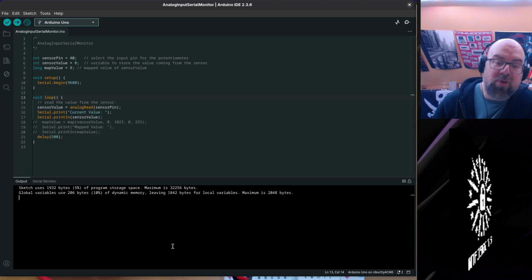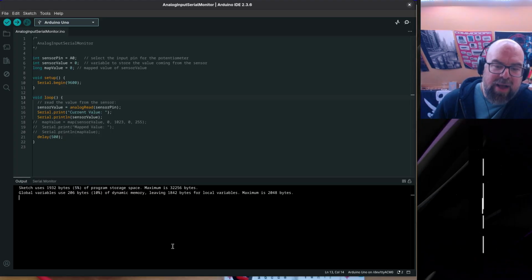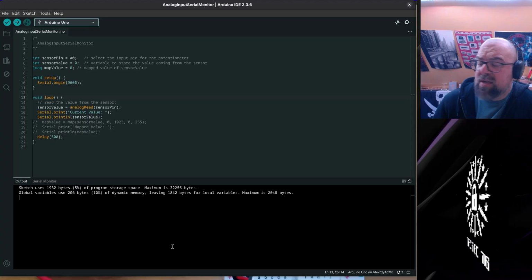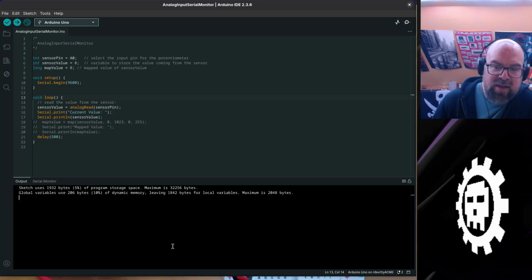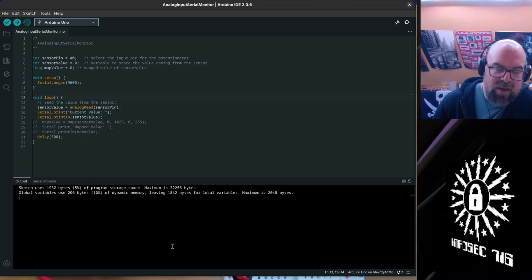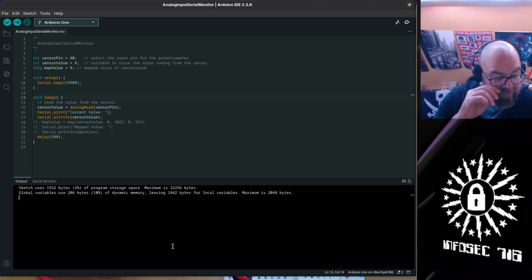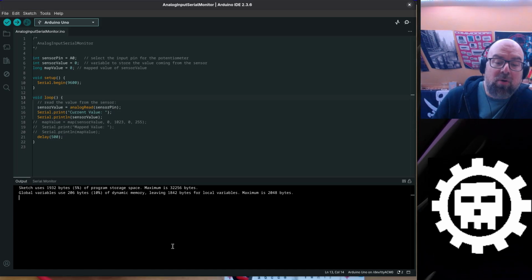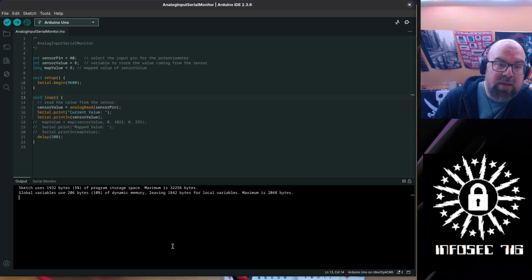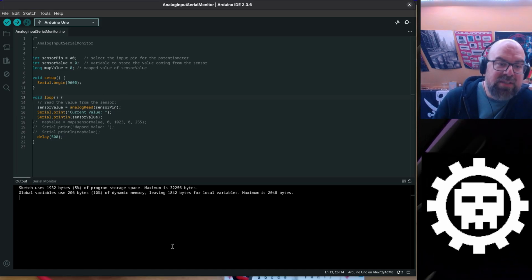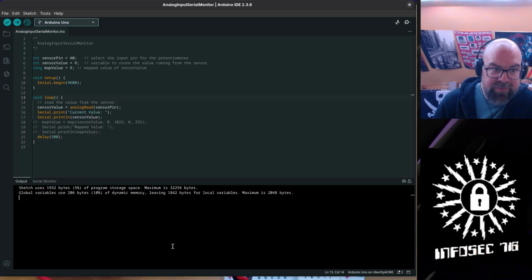It can really only produce a digital signal, but by turning it on and off, think like a strobe light, it can simulate an analog signal, by leaving it on and off for particular lengths of time. Anyway, so a PWM output can have a value between 0 and 255.